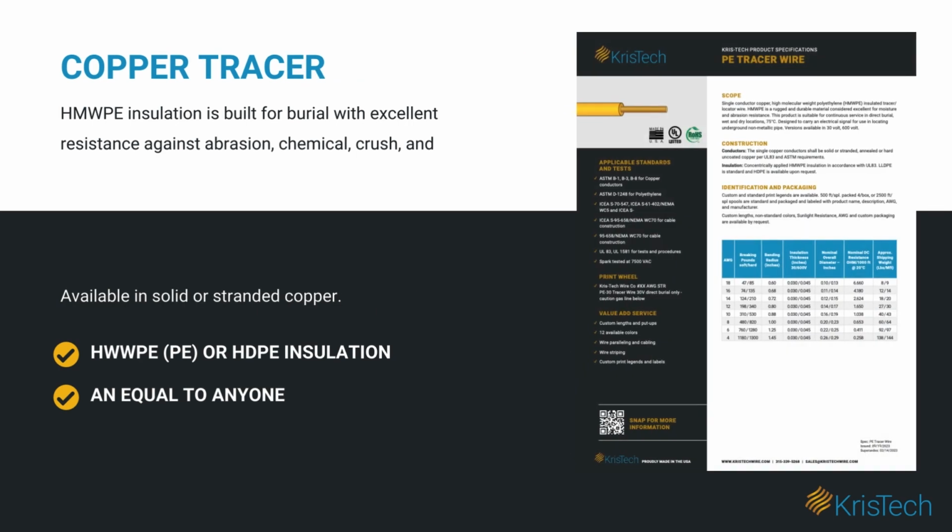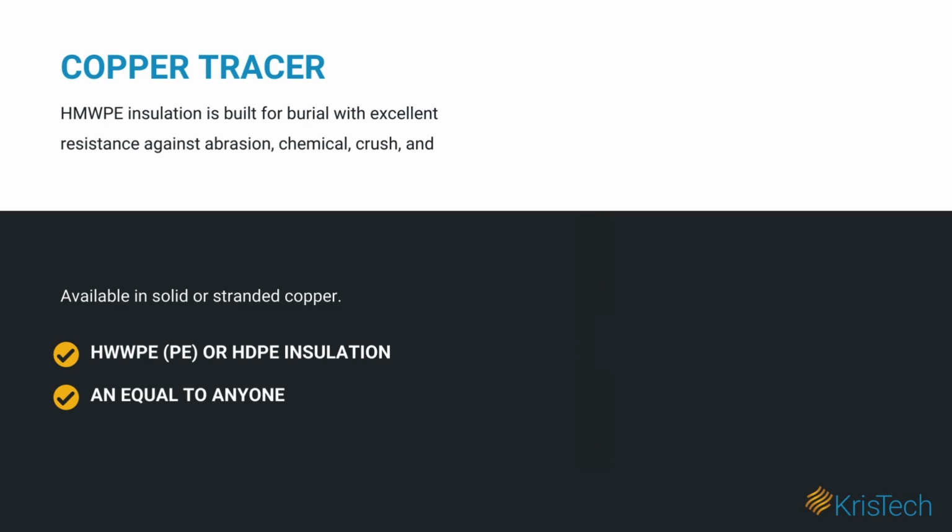In comparison, copper PE tracer wire has the same jacket and construction characteristics as copper-clad steel, except it has a lower break load strength. As stated previously, copper is a better conductor and it is also much more flexible and easier to work with compared to copper-clad steel. Copper-clad steel can be stiff depending on the version and springy by nature, whereas copper has a better bending radius.